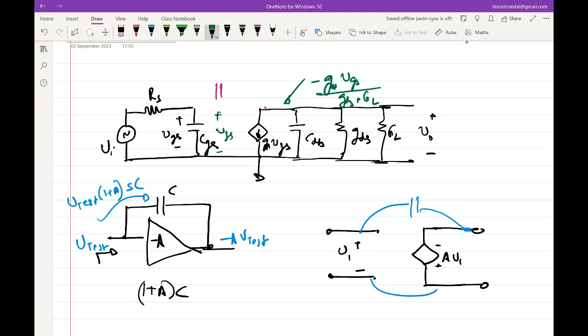So there is a gain relationship between two terminals of the common source amplifier, the input and the output, and they are 180 degrees out of phase, right? So if that is true, then we can expect some sort of Miller effect if we put back a capacitor between the input and the output port. So that is why we are talking about the Miller effect.